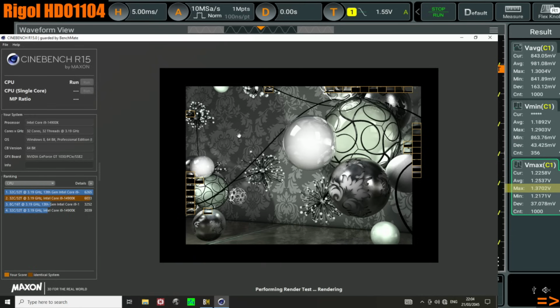Because Intel and AMD and NVIDIA don't want to spend a month verifying that every single possible sequence of instructions is going to execute correctly when the voltage is within 5 millivolts of being unstable. So instead, they ship the CPU with, say, 100 millivolts of margin on it easily, probably more than that. They'll ship the chip with 50, 100, maybe 150 millivolts of safety margin if you get really lucky, or unlucky depending on how you look at it, right?